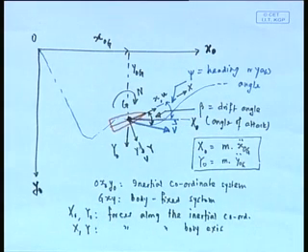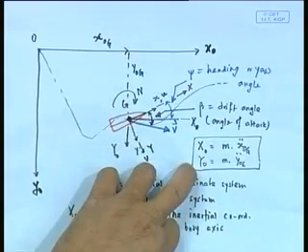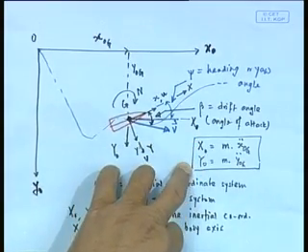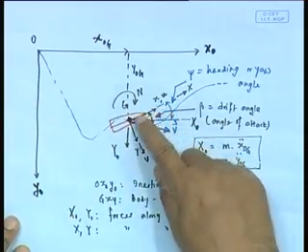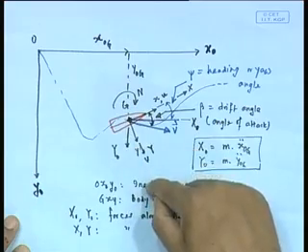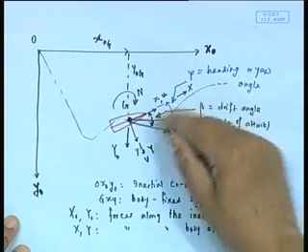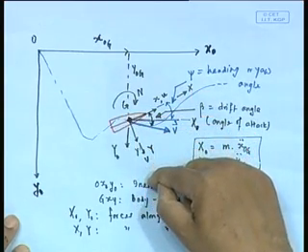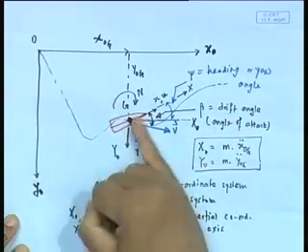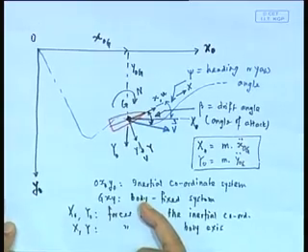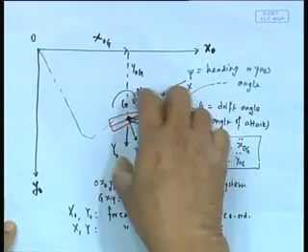This of course will not have completed my story at all, because I have established my equation of motion, but my most important point that I have to ask myself was, what is this x0 and y0, because this is the fluid force that is coming. And in that again I am much better asking myself what is my x and y, because x and y would tell me this x is nothing but my resistance force, y is my sway force. See, if I were to call what is my force in x direction and y direction, the x0 direction, y0 direction, it is much more confusing, because the ship can be oriented on that.